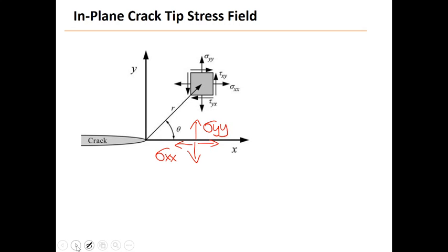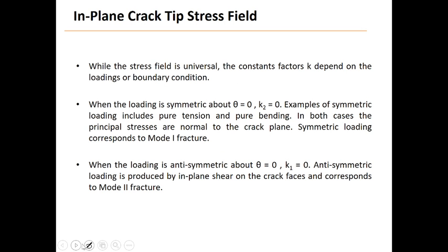Now we come down to the next thing that we want to talk about, which is these factors, this small k, right? So we can separate two types of loading that we apply to figure out the corresponding k for different types of loading, because we said that the loadings only influence the crack tip stress field through k, right? And we found out two things, right?